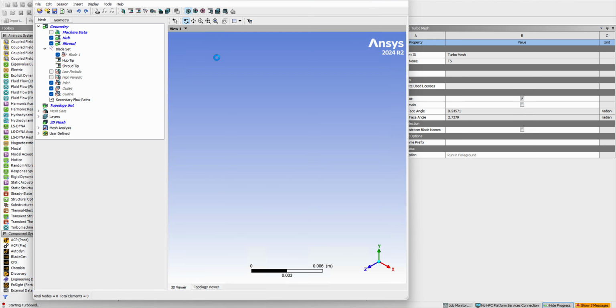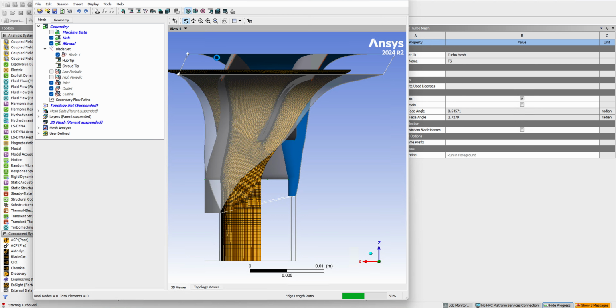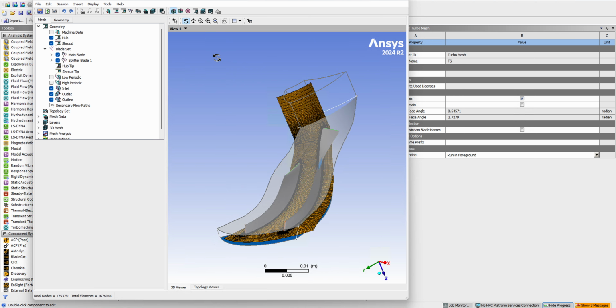Then you would go into TurboGrid. What we want is probably no warnings or errors from TurboGrid. There are some values you can play with to make TurboGrid happy. Mesh quality is a very important aspect of simulation. However, I don't believe our team currently has enough knowledge on how to create a good mesh or even tell what is a good mesh. So here we're just going to follow the TurboGrid tutorial and make the internal check of TurboGrid happy.